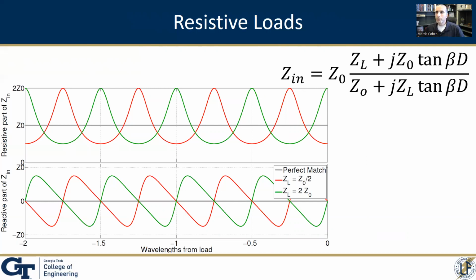So with that, we can conclude we've sort of generalized the ability to characterize the voltages and currents on the transmission lines for any resistor value. And if we know basically the ratio of the load resistance to the line impedance, that sort of gives us the characteristics that are going to appear in our line. The standing wave ratio, the input impedance as a function of length, the quarter wave point, all those things. In the next portion, we're going to talk about arbitrary loads where we have some combination of resistors and capacitors.